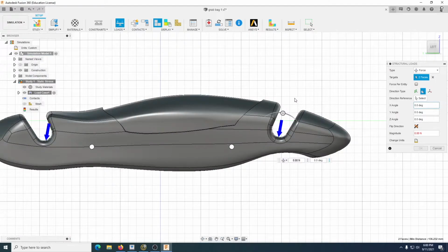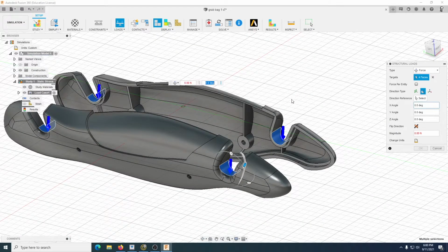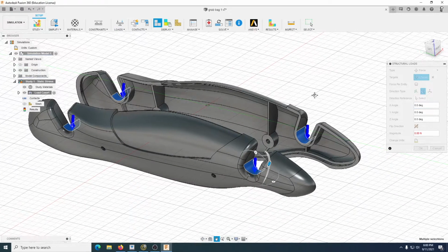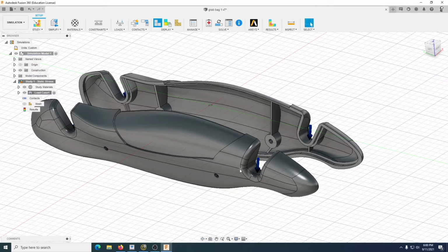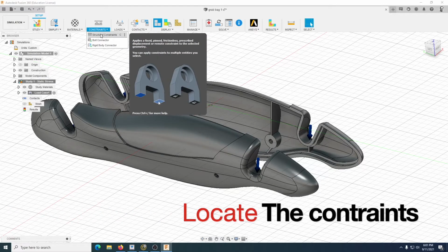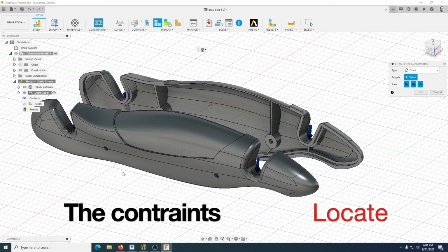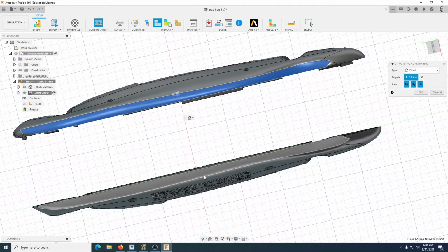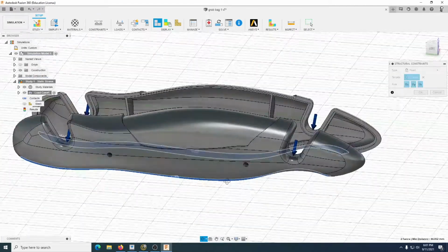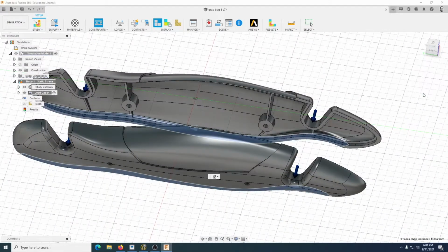According to the web, the maximum weight carry bag can take is 250. Now you're not going to be using this to carry 1 bag. You're going to be using this to carry maybe 2 bags, so 500. So there's going to be 500 newtons. Okay, so we've got this one with 250, this one with 250. Now the constraints are my structural constraints, and of course this is where your hand is, so that and that should be locking it in place.